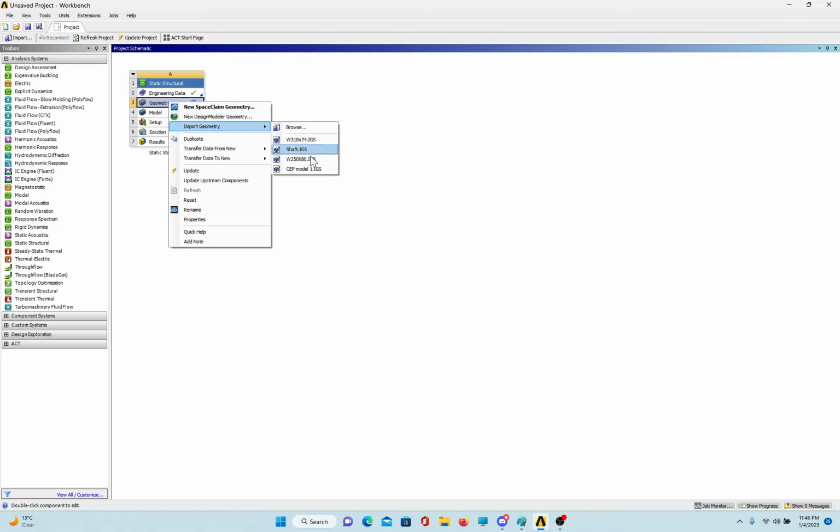You can see that I've imported some geometries in ANSYS Workbench in the IGS format. As you know, SolidWorks saves files in its own format, or CATIA does something like this, but make sure that you export your geometry in the IGS format before importing it into ANSYS. Otherwise, ANSYS will not import it or will give some errors. But right now we are going to make our geometry in the design modeler of ANSYS. Okay, so go to design modeler.